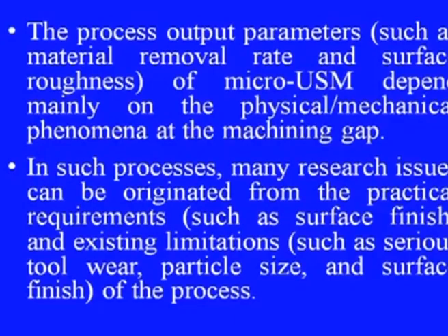The process output parameters such as material removal rate and surface roughness depend mainly on the physical or mechanical phenomenon at the machining gap. So, that also needs to be evaluated. In such processes, many research issues can originate from practical requirements such as surface finish and existing limitations such as serious tool wear, particle size and surface finish of the process. So, this needs to be sorted out on a case to case basis.